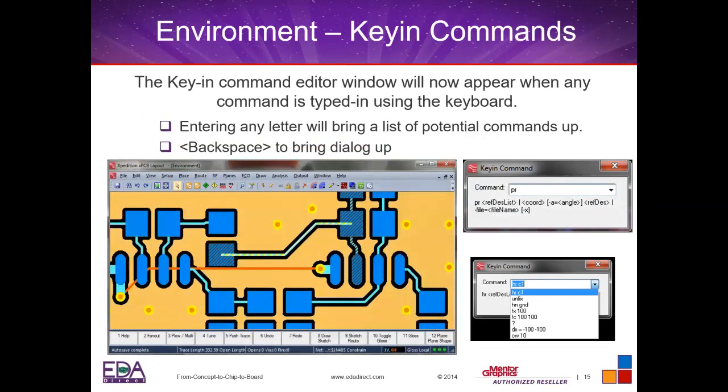Also have key-in commands. So those are going to be available to you. Modeless commands like we have in the PADS tools. You can just type in, for example, if you want to change the width of a component, we can just say change width and give it the actual width of that component. So you will have full capacity to create your own environment with your key-in commands, if you prefer that rather than using your mouse.